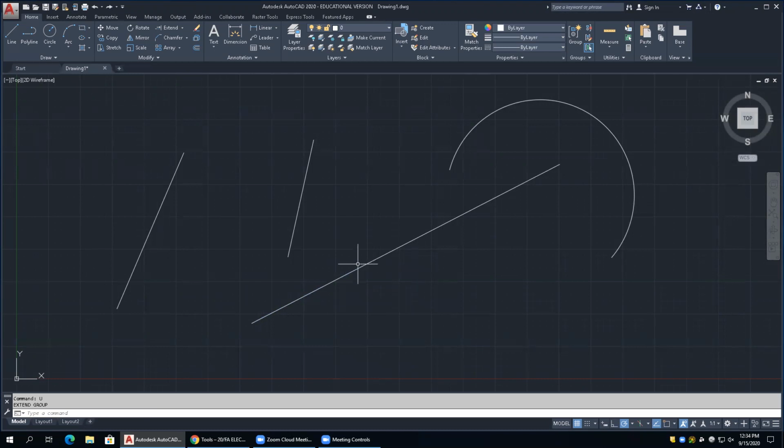So here's what I'm going to do, I'm going to take this line, I'm just going to click right here, and I'm going to move it till it crosses through those objects. You guys can do the same thing, or you can just draw a line that comes through objects. Don't care really how you do it. So trim, just like extend, requires your boundary, but they call the boundary for a trim a cutting edge. And then you're going to have the objects that you want to cut.